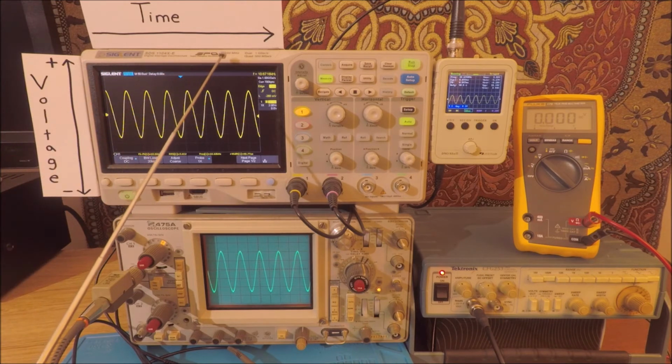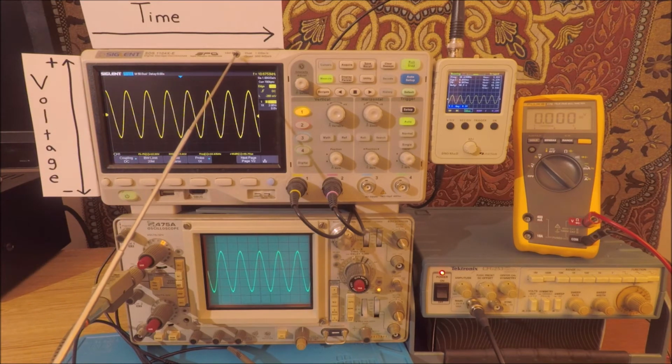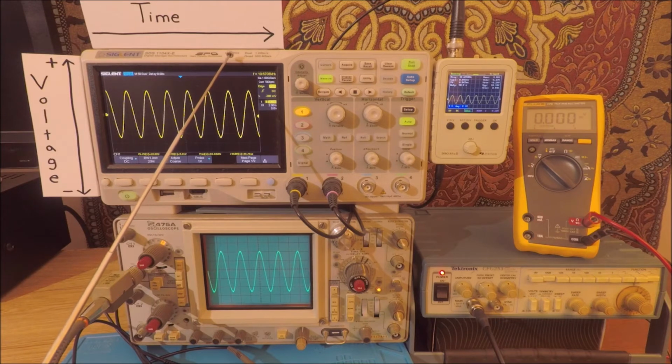It's telling us right on the tag 100 megahertz. So any signal that we have greater than 100 megahertz, this scope will not be able to represent accurately. Every oscilloscope is a system, and so it is going to have an inherent transfer function that is going to have a finite or limited pass band that it can measure to.